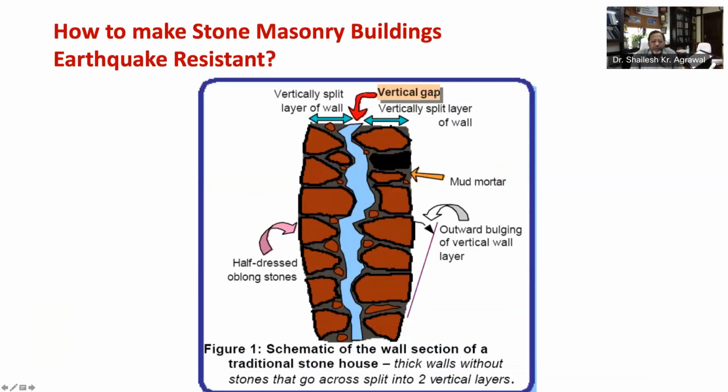In a typical rural stone house construction in India, the stone masonry walls are normally quite thick, the thickness ranging from 600 mm to 1200 mm. These walls are built using rounded stones from river beds with mud mortar. The walls are constructed generally with stones placed in random manner and hence do not have the usual layers or courses as seen in brick masonry walls.